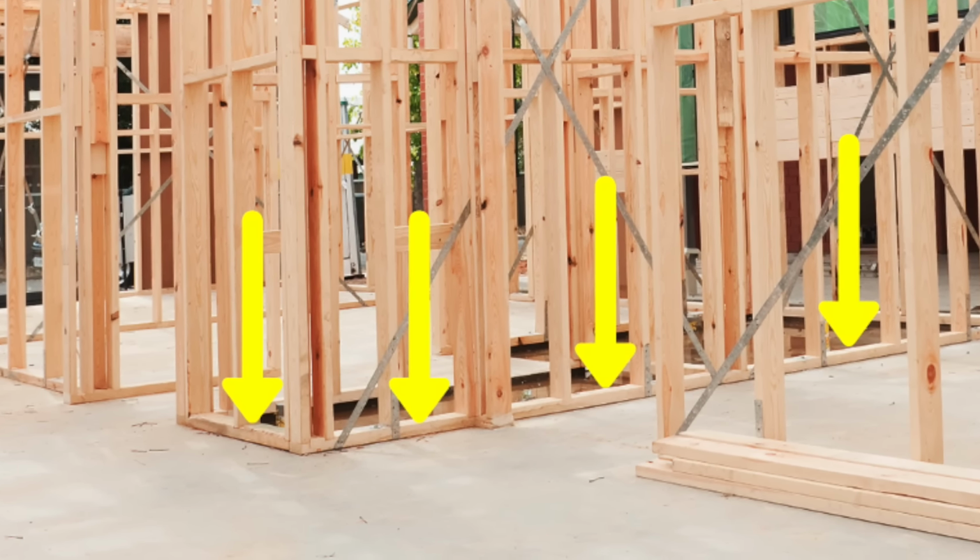So you have a bottom plate beneath the wall, and you have top plates at the top of the wall. Top plates are typically doubled up for strength. We call them double plates. Adding top and bottom plates to vertical studs lets us build our walls laying down and then stand them up into place. It turns the whole wall into a rigid unit that acts as one piece. Studs and plates are virtually continuous in a wall, except where they're interrupted by doors and windows.